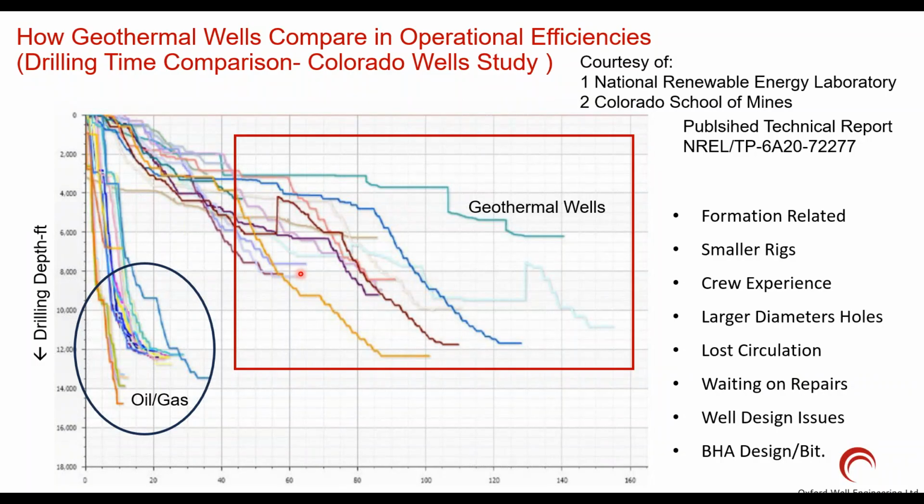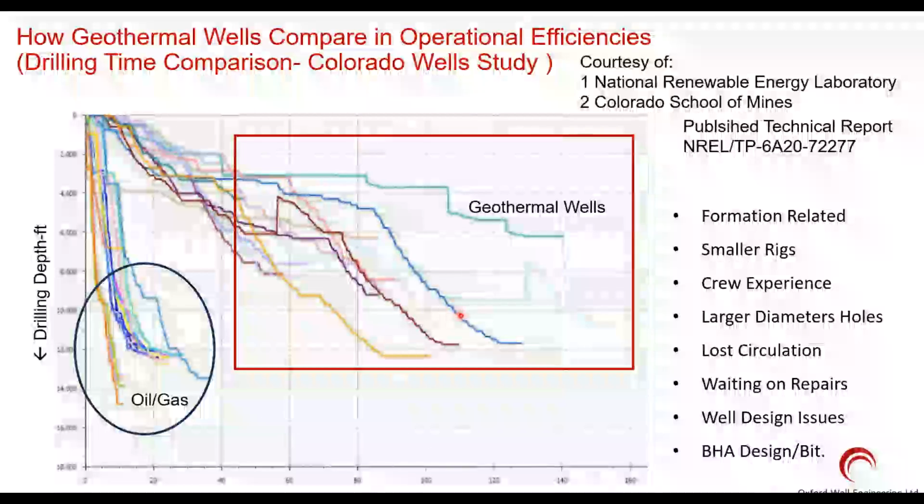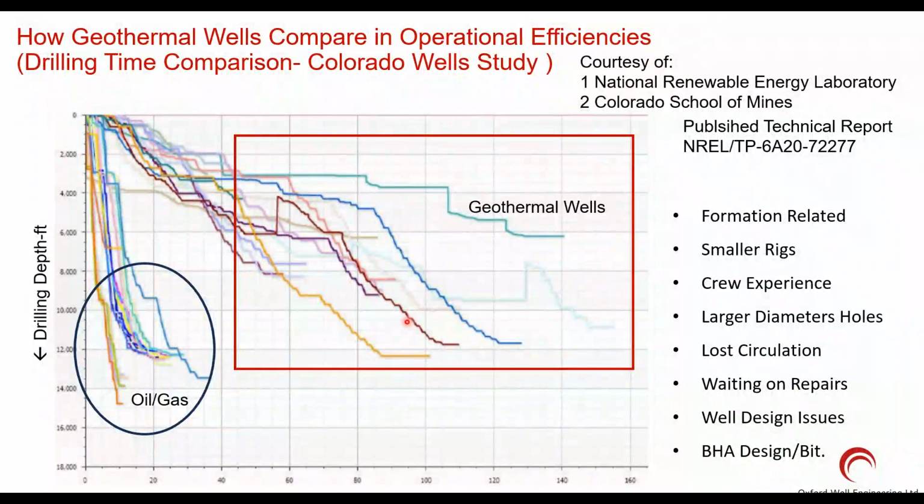But good news here: when they get going, the slope is not terribly off. Similar slope means the rate of penetration, ROP, for example, is okay. It's not so bad. It's just they could not drill continuously. They have run into problems. They stopped. That's why the flat time comes in.